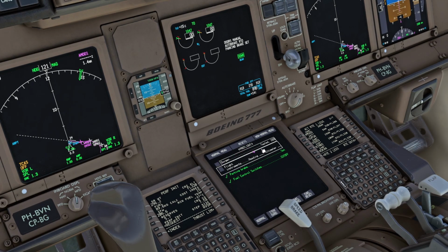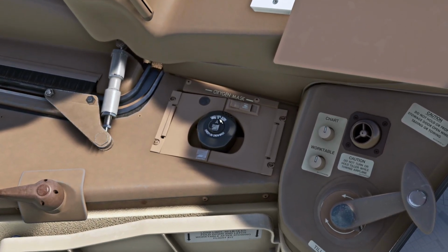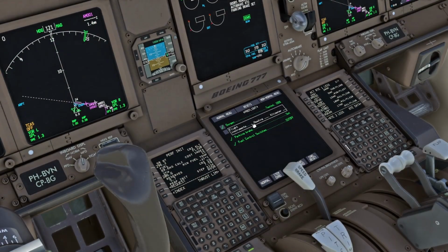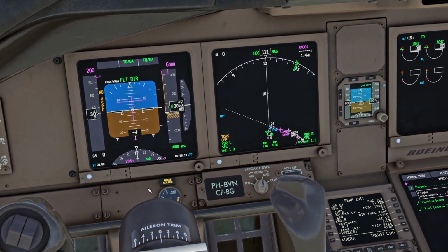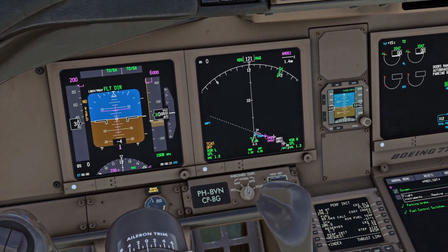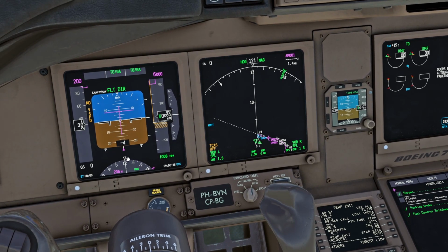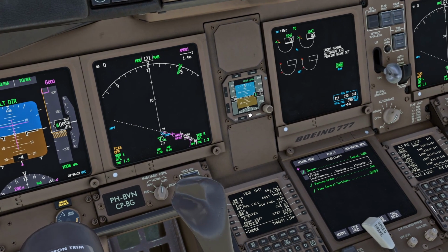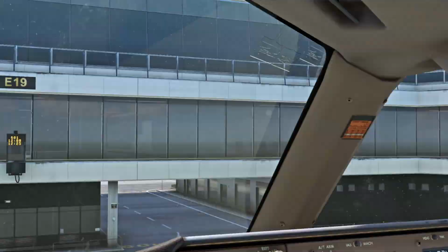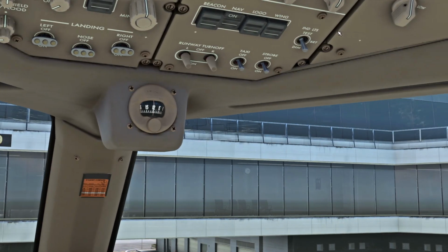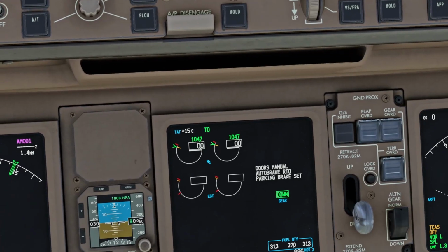The oxygen is tested 100%. Again, these are the oxygen masks that we've tested before and they are set to 100%. Then we have the flight instruments. Make sure we give a good view of all the heading and altitude information on the different displays. So we have a heading of 121 here on the standby display as well, on the first officer side as well. Make sure you also take the compass with that. It should correspond sort of to your current heading.